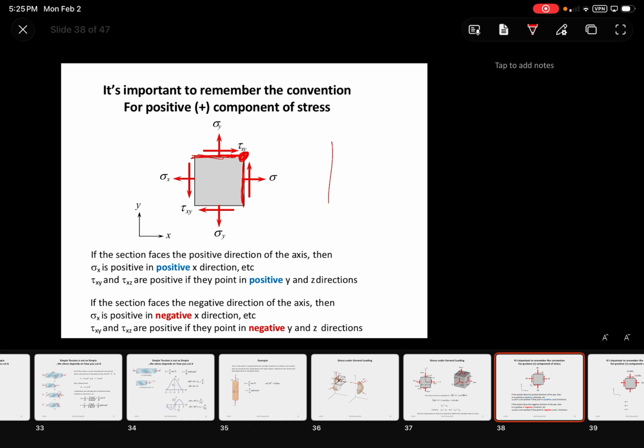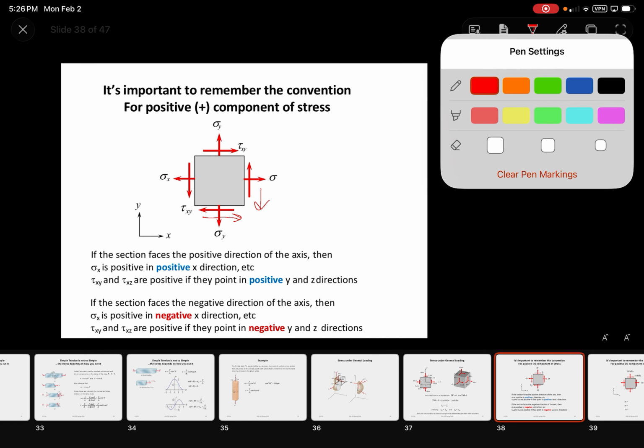You could think of it as if you've got a plot here. This is your x and y curve. You have a positive value and a positive value leading to there, so it's a positive value. In a similar way, when you have two points going negative, negative to a negative, what's a negative multiplied by a negative? It's a positive value. Now, if we were to look at stress from a different orientation, for example, if we had a shear stress going that way and a shear stress going that way, one is going positive right, one is going negative down. Positive times a negative is a negative. I've got some examples coming up on the next slide.